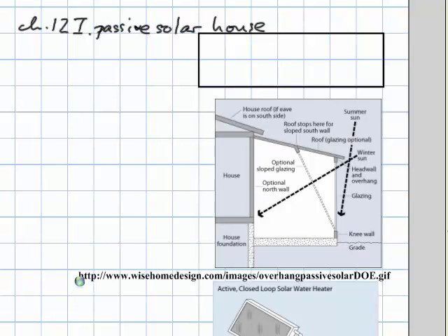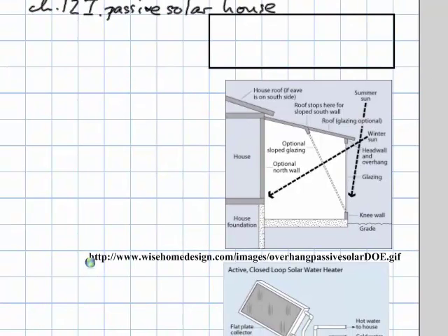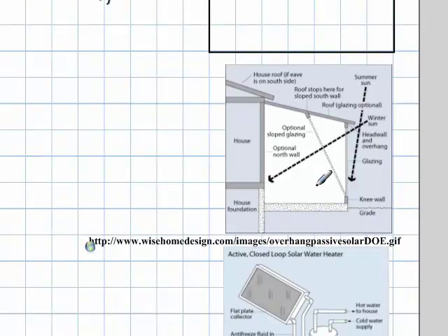So here I took a couple of images off the internet, and let's see what shows here. This is kind of an original passive solar house. There's no water in here, and the winter sun, as it says here, would heat the inside of that room, and then you would have pretty good heavy, massive rock here that would absorb that heat from the winter sun and then give it to the rest of the house, radiated out here and radiated back into this particular room.